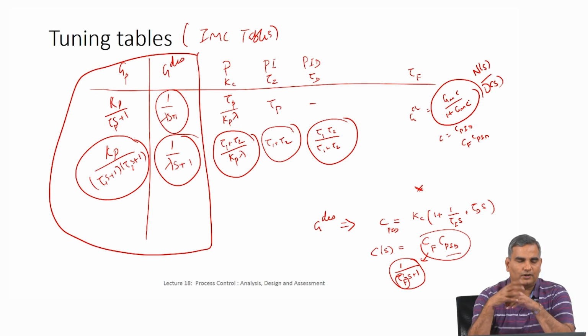if the sensors measuring your outputs are noisy, then your controller will chatter a little bit. Of course, one way to avoid that is to smooth the measurement, but if you smooth the measurement, then the effect of the future actually gets lost a little bit in that process. So conceptually PID, while it sounds great, in real implementation there are issues with some of these. So unless there is a very specific case where you use this, typically PID is not used as much.